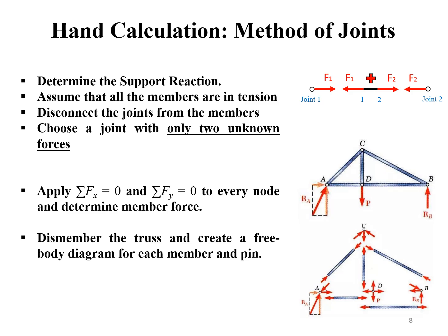To be able to design or analyze a truss, we need to be able to determine the force in each of its members. This allows us to check that the members can carry the loads without failing, or gives us the information we need to select the best cross-section for each of the members. There are two main methods we can use to do this: the method of joints and the method of sections.